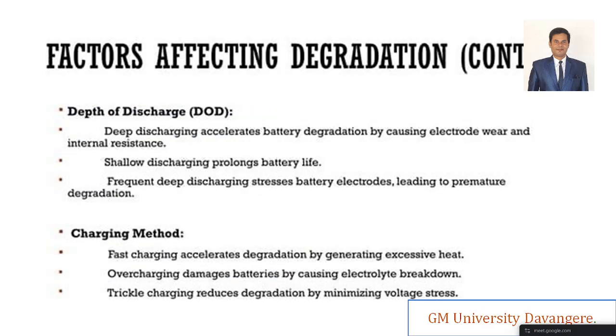So that is what you have to think about in the charging method. We should not go for fast charging, right? Fast charging will accelerate the degradation much earlier, and it will generate excess heat also, right? So we don't expect DC fast charging. It will draw heavy current and have excessive heat also, and it will try to accelerate both the capacity fade and the power fade also, right? So these are the various reasons.